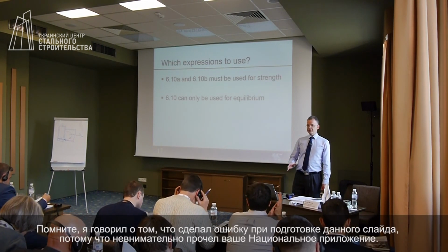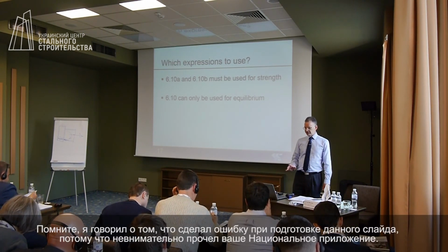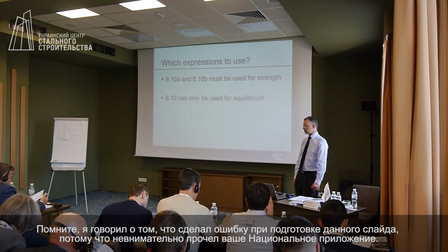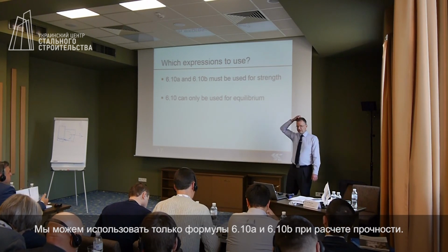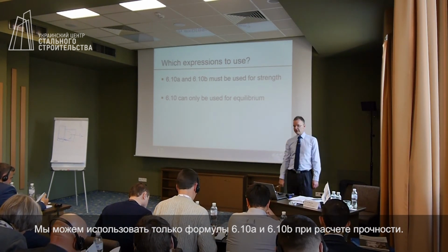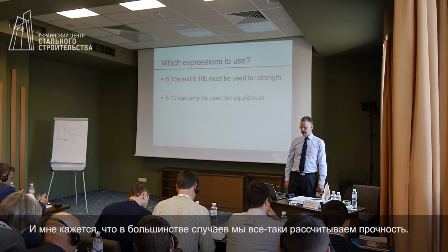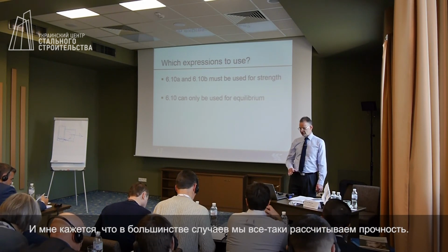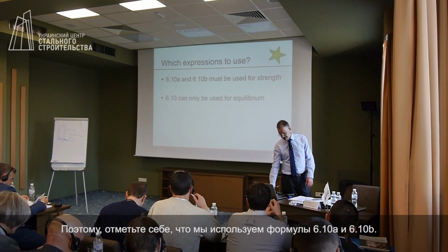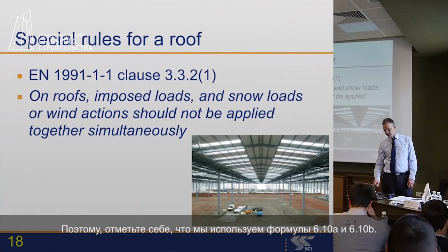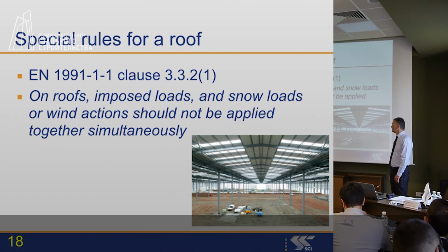Final reminder from me, remember I made a mistake in preparing these slides because I didn't pay enough attention to your national annex. You can only use 610A and 610B when you're calculating strength. And I believe that most of the time we are interested in strength. So please highlight the fact that 610A and 610B are the expressions that you should use.